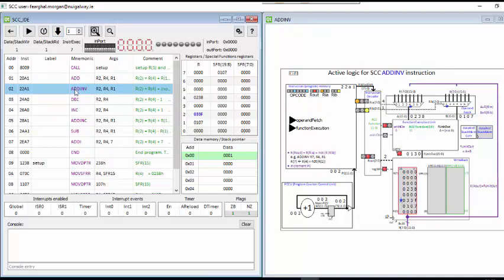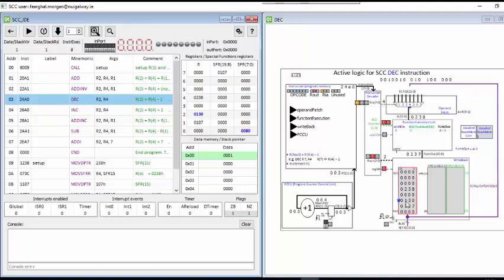Now I have different instruction, same destination, same source parameters 4 and 1. This time RFC in is a 0, ALU function is 10, and that selects A plus not B, and the answer is 130. That's again written to register 2, and the answer is 130. You can see that over here as well.